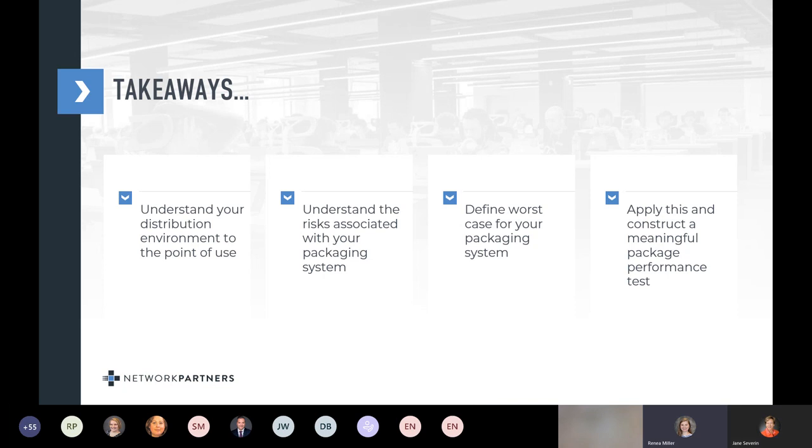Can concentrated impact test be eliminated by reducing packaging size? In other words, making the package smaller? As far as I know at this point, the exclusion of that is containers under 275 pound or 44 ECT. I could be wrong, but I'm not aware of a size limitation on that. Hi, Jen. Noel Gibbons here. Yeah, you're correct. It's dependent on the material in the actual shipper box that's being used, not the actual size. Thanks, Noel.